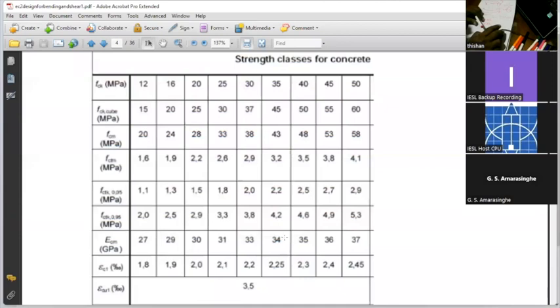And you can also see the elastic modulus is about 30. And so if you want to even optimize further, you can go for something like 55-45, and then the elastic modulus will be 36, and you get a slightly little higher allowable stress here.